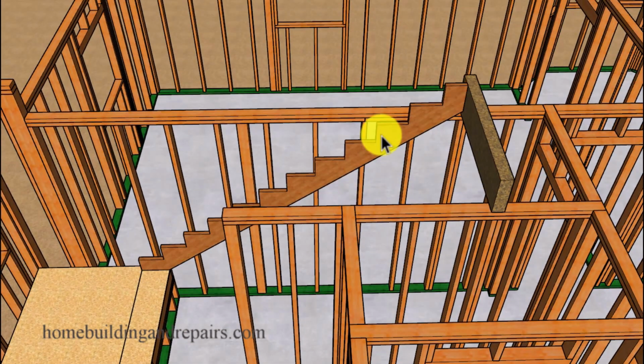And like I already said, I can't tell you how many jobs I come to where the stair stringer is off an inch or more because somebody built the floor first or didn't know how to locate the stair headout. So if you're not really good with math, your stair stringer measurements might be off a little bit, or you're just looking for the easiest way to locate the support beam or stair headout in the floor framing, then this just might be your best option.